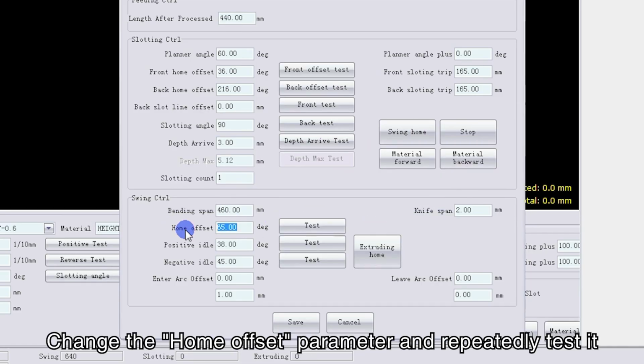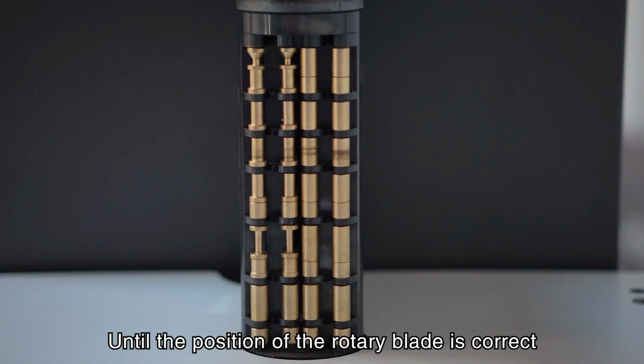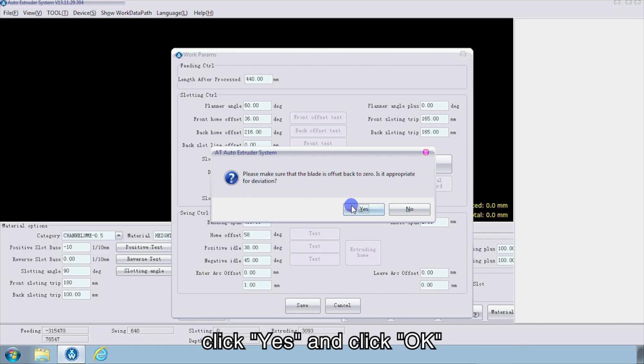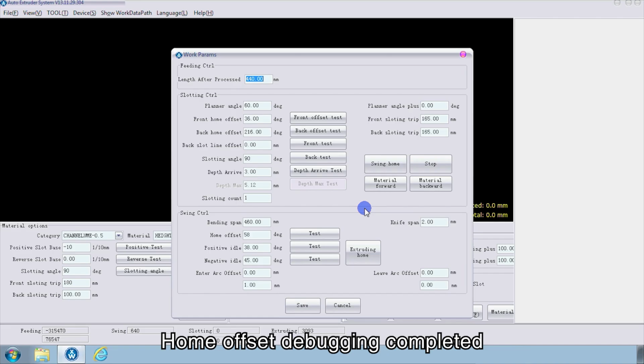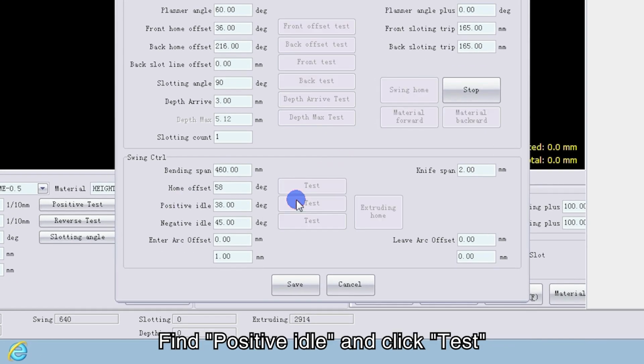Change the home offset parameter and repeatedly test it, until the position of the rotary blade is correct, then click yes and click OK. Home offset debugging completed. Find positive idle and click test.